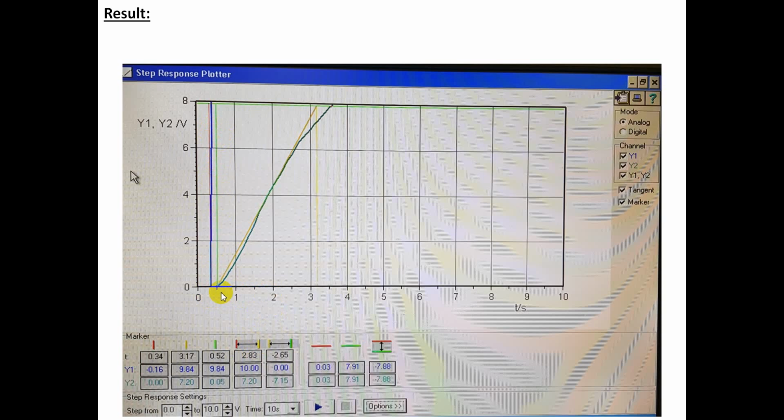that this area between red from here up till the yellow is basically 2.83, and the area between green and this one is 2.65. So you can subtract it from this value, so you will get something maybe like, for example, 0.18 or something, whatever. Okay, you can subtract it, so you are going to get basically here the Tu, and then this will be the Tg. Okay, this was our experiment basically.